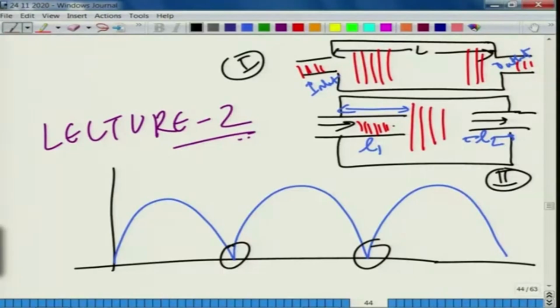So, when the acoustic wave is incident at the interface of the extended inlet and the chamber, a part of that is diverted towards the annular cavity and part of that goes here. But before that, let us figure out the resonance that the wave sees right at this section marked in yellow color. What is the impedance? So, remember this is a quarter wave resonator.